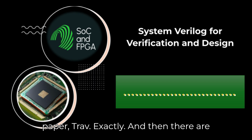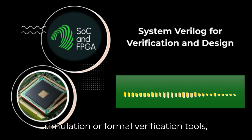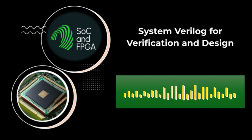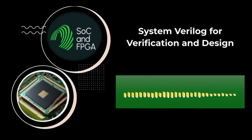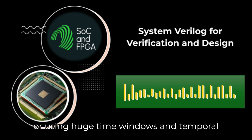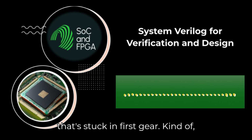Exactly. And then there are performance hazards. You can write SystemVerilog code that is functionally correct but just runs incredibly slowly in simulation or formal verification tools, maybe creating way too many assertions on individual bits instead of wider buses, or using huge time windows in temporal assertions. It can kill your verification throughput. It sounds like a supercar that's stuck in first gear.